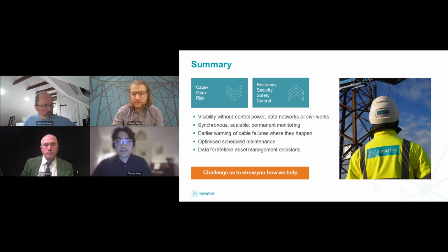So that means that if you're seeing hotspots in your cable, you'll see them coming much earlier. That DTS system also likely has an OTDR, optical time domain reflectometer, which means that you can look for breakages in the fiber or points in the fiber that have actually broken down if you have a really severe cable failure. So if you see that there's a breakage somewhere along that cable, you can then diagnose afterwards that that cable has failed somewhere along that route where you see that breakage in the fiber. Hope that answers the question.